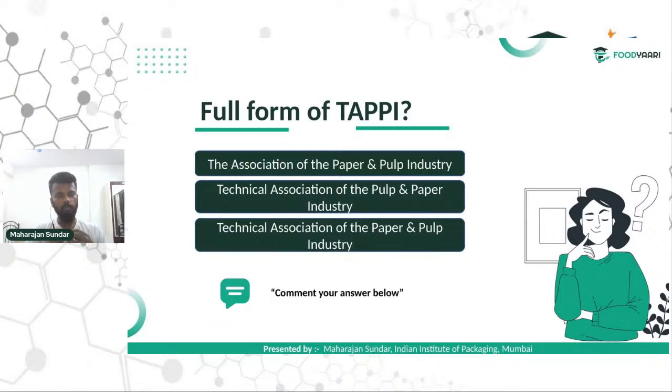There is an equipment called a burst tester, where pressure will be applied. The sample will be kept here, and there will be a hole behind it. It will be held here and clamped. There is a movable upper clamp and a lower fixed clamp, through which forced air will be passed. Is it visible?